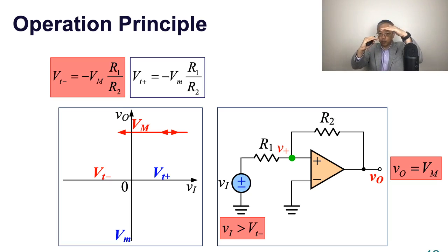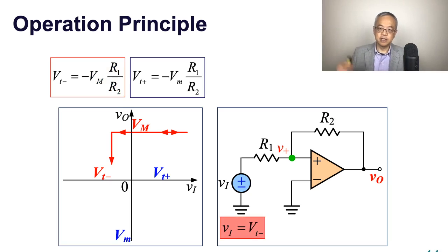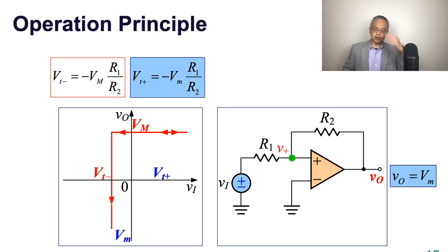This is ground. So when you reach the ground, which is associated with the threshold voltage, the bar on the top of the hill, then what? If you lower VI just a little bit, then the switch happens. VO, the output, goes from high to low, from red to blue. So the moment the output switches, remember this subtle but very important point. This is the key. When the output changes state, the threshold voltage will change immediately and accordingly.